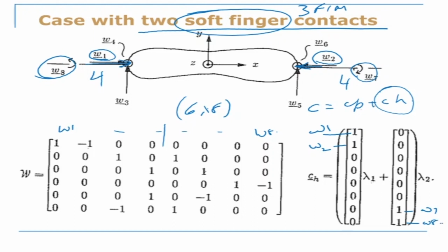So the internal forces are this one plus that one. Okay, so internal force and internal moment. In this case, we have internal force and we have an internal moment. Apart from this, if you want to manipulate the object, now you need to apply more forces. You need to apply Cp also. So this is for motion or moving the object. This is for equilibrium, static equilibrium. Sorry, this is only for grasping.